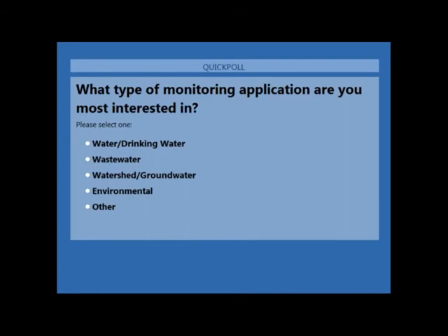This goes back to the communication technologies. We had a question from Charlie Platt: what about Zigbee? Yeah, so Zigbee is a mesh radio communication network. Mesh means that you deploy a lot of devices and they transmit the signals. The data actually hops from one device to another until it reaches the final destination of that data packet.